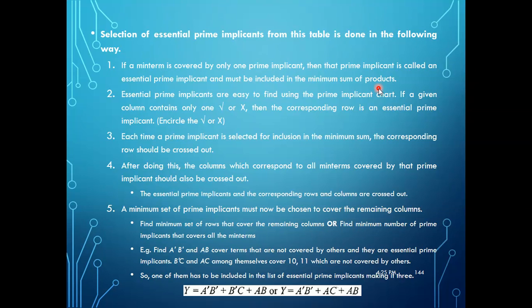Okay, it can be followed for the next stages also, but usually in the exam you get up to stage 3 only. Okay, so here in this particular problem, the next step is you have to form a different table where you are going to write the prime implicants. Okay, prime implicants are selected from the previous step. Okay, so which terms you have not checked. After combining so many combinations, some terms will be left out without combining. Those terms are considered prime implicants that you have to choose for the next step.